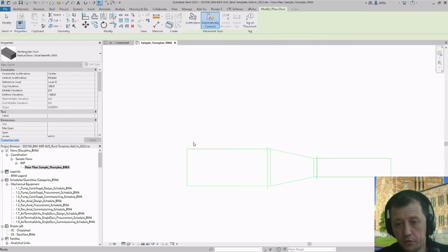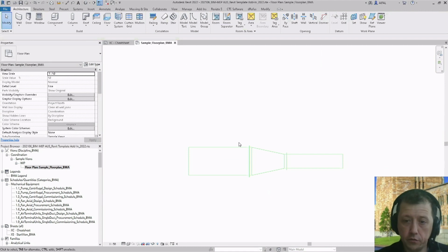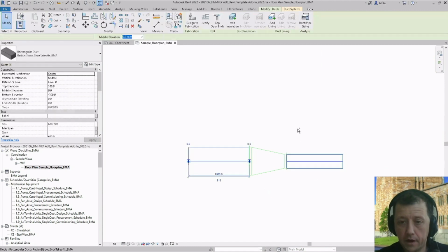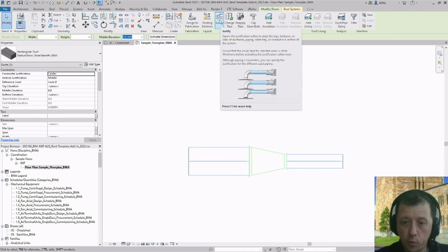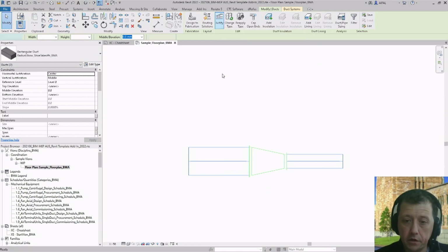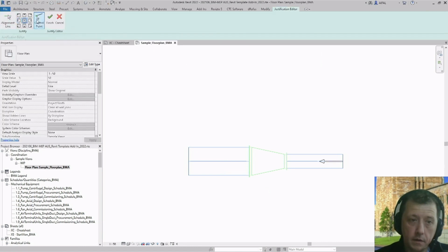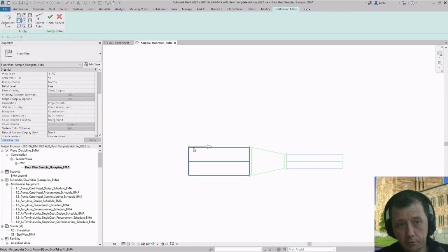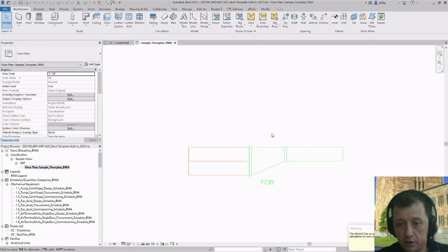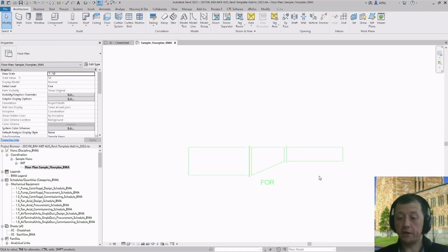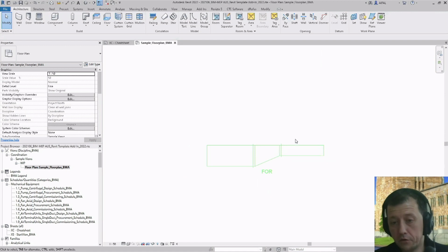So, for example, with that transition, if you want to use the justify command that we have here in Revit with that concentric family, or at the moment concentric family, we go justify, just change over here. That is my alignment line, and then I'll go finish. And I can use the same fitting for both situations, for concentric and eccentric.